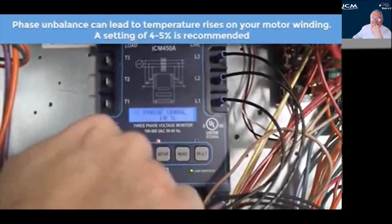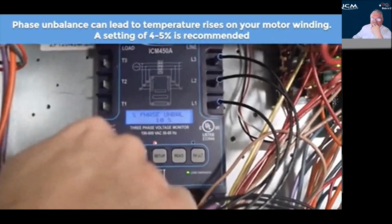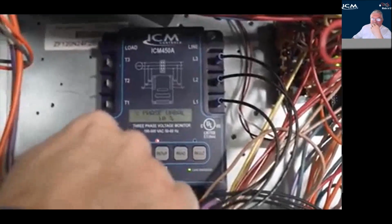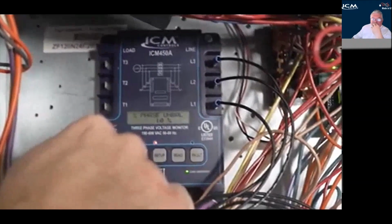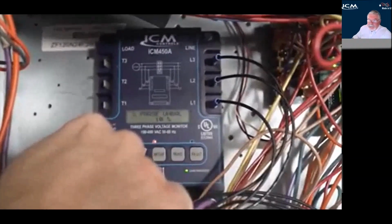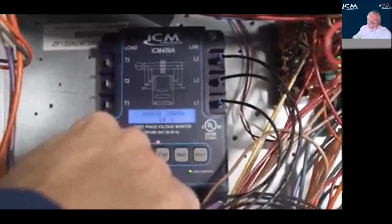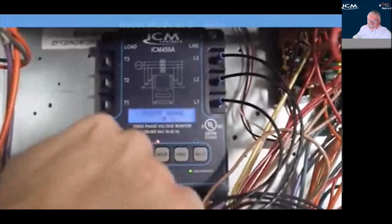Next is your phase unbalance. That's the 10% as it's monitoring the difference between the three different lines as to what's an allowable out of range. So we'll get that to about 5%.